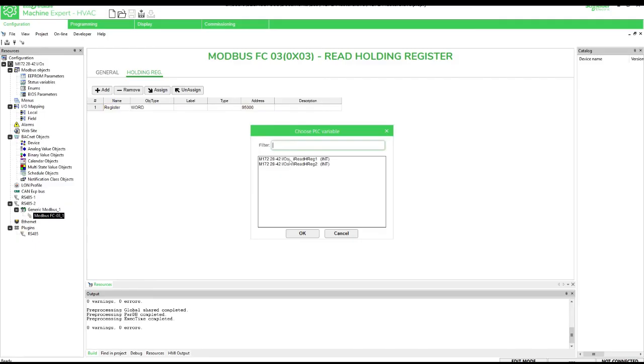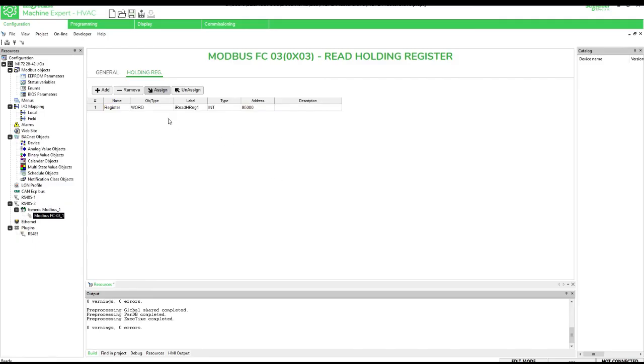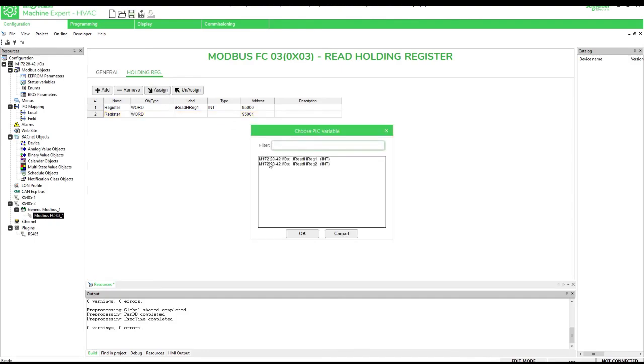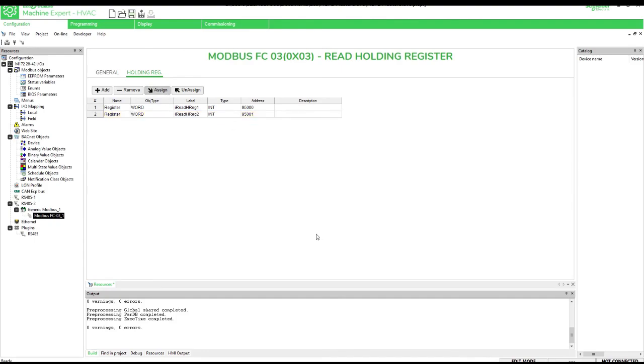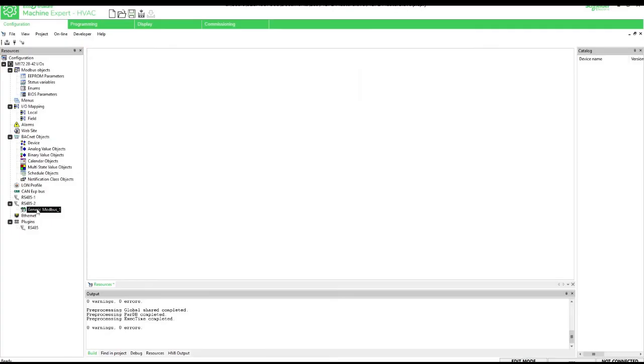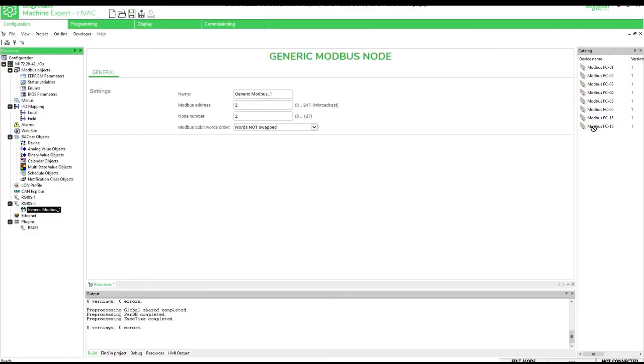The PLC sends all write commands before read commands. If variables are not initialized, the PLC writes zeros by default. The address and variable must match for both read and write functions. If the slave is an actuator without display, or if configuration changes are not allowed, it is necessary to copy EEPROM parameter values into variables during startup.